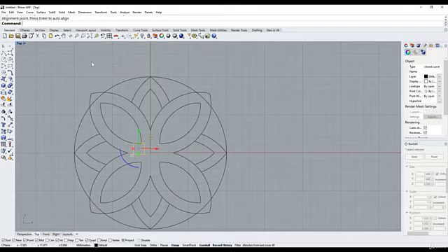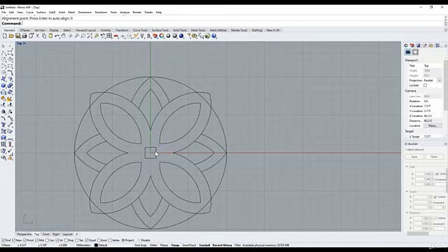Don't know what's happened there, sorry. I'll right mouse button to run that again. So horizontal center from the alignment point. Oh, I guess I push 0 enter and run that command again, and this time it's the vertical center, and that is 0 enter. So now we've got our center at the horizontal center and the vertical center.